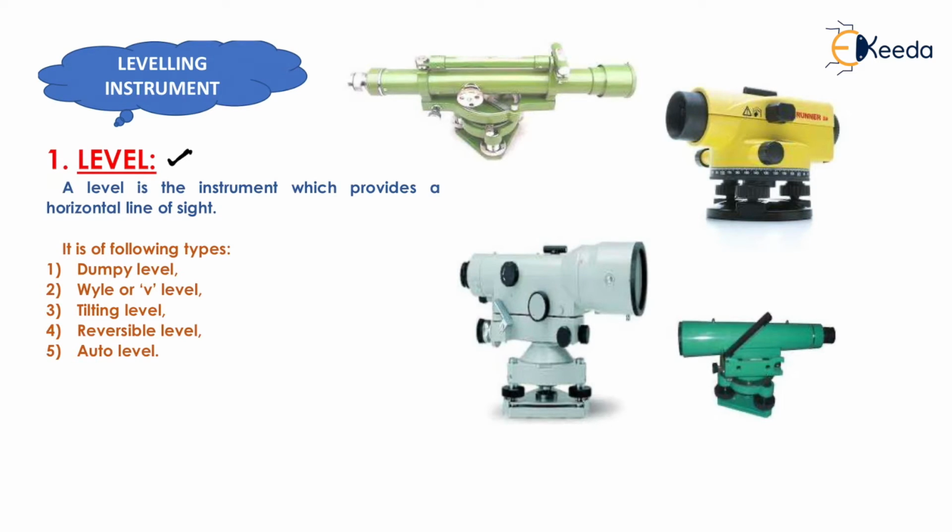Now the next one is the instrument which we use in our leveling, that is the level. You have all seen in your life various types of level, that is the dumpy level, which is shown here, the Wye or Y level, tilting level, which is shown here, reversible level, which is shown here, and auto level, which is shown here. There are various types of level which we use in our leveling work. Nowadays the auto level is mostly used because it is a much more accurate instrument as compared to the dumpy level, Y level, tilting level, or reversible level. That's why we use the auto level nowadays.